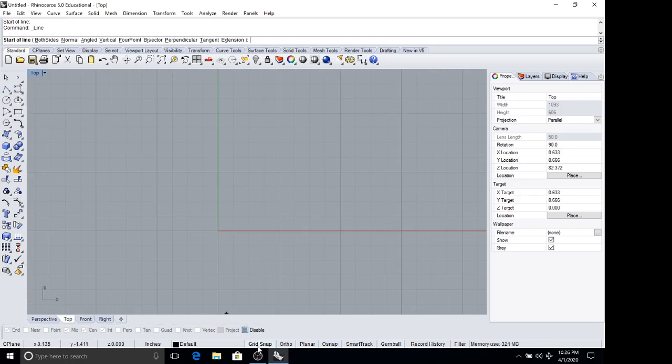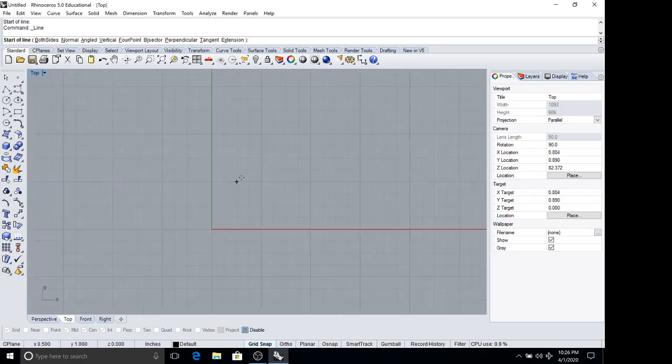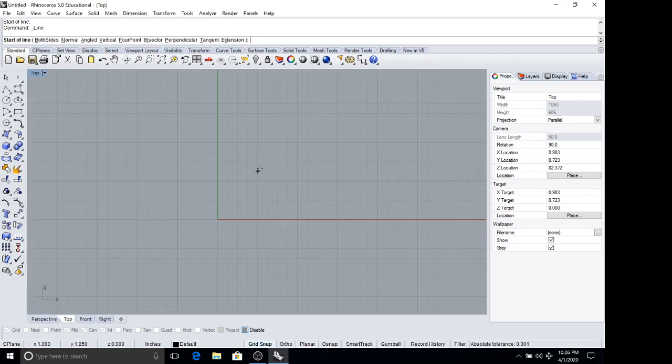So for the grid snap, it's going to snap to the nearest 1/4 of an inch on the grid. So this can be really useful if you're drawing something where all the dimensions are made out of whole numbers, or at least numbers to within the nearest 1/4 of an inch. But it can also kind of get in your way if you're trying to draw something based off of geometry and not off of measurements. So I'm going to turn that guy off now.